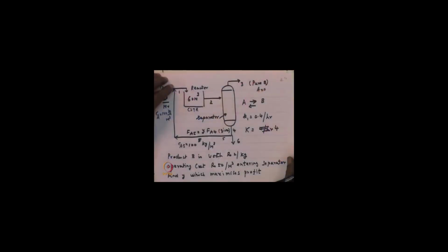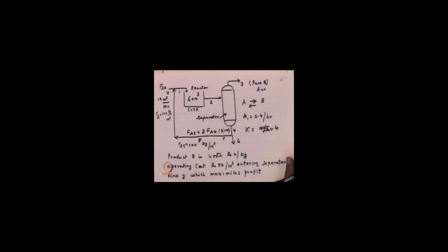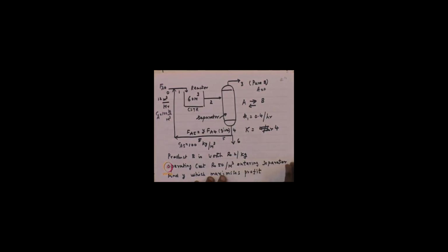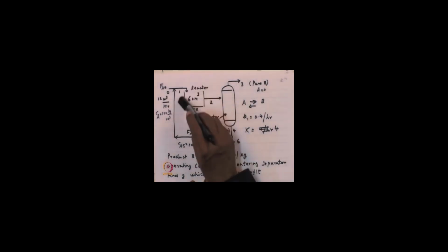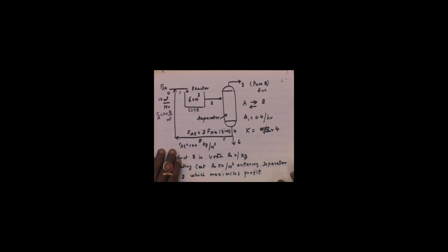Notice that our effort is to put every variable of interest in terms of parameters, process variables, which we are interested in, so that we can do our optimization properly. Okay. What we have done so far is that we have expressed concentrations at position 1, concentrations at position 2, volumetric flow at position 1, volumetric flow at position 2. That means, whatever affects the process, the reactor, all that we have expressed in terms of alpha and y. Therefore, we are now in a position to write the design equation for this reaction equipment, so that we can understand how they come together to affect the process.